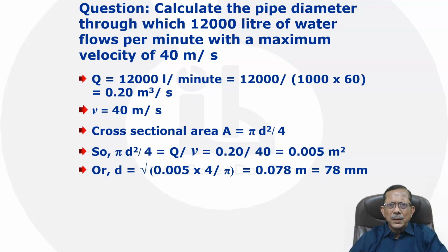So you have got 25 NB or 50 NB. You can have 40 NB, which is usually translated to 1.5 inch. You can have 80 NB. Yes, you can have 80 NB. That is 3-inch pipe, and you can have 100 NB. You also have 65 NB.